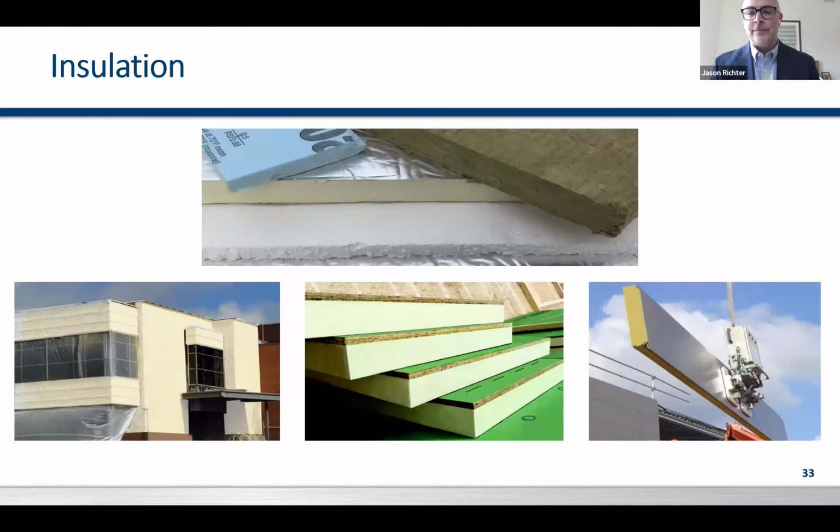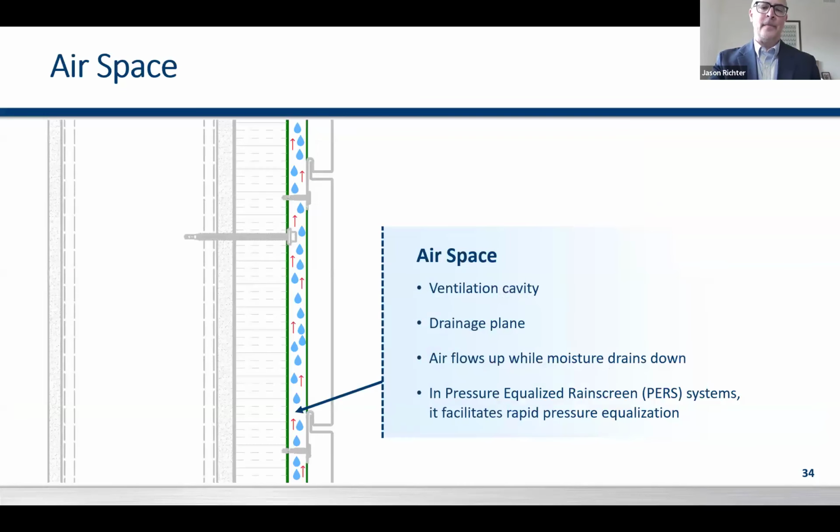So a lot of the standard types of insulation you'll see nowadays, the blue board, the polyiso, the foil lined as well. More and more you're seeing spray foam applications out there in the construction industry as well. Your SIPs panels where you have laminated exterior grade plywood with self-adhesive sheathing or WRBs, sorry, on top of that. And then the Cadillac of the industry, if you will, are insulated metal wall panels. Those can be fire rated with mineral wool cores or standard with polyiso infill.